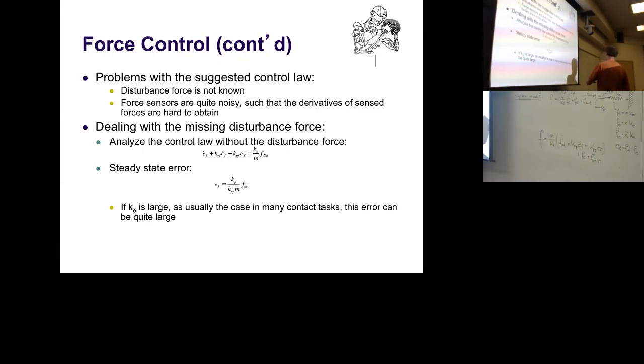The other thing that is annoying is we are basically dealing with force derivatives here. Now, if you ever looked at a force sensor, it will show you a plot over time. So this is the force over time. This is what you measure at a constant force level. And this thing looks like this. So usually with quite some high amplitude noise. That's just a process of measuring forces. It's not a very clean process.